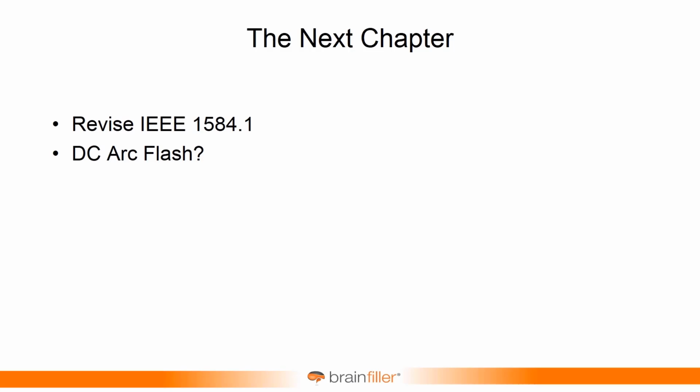The lower current cutoff, well, right now it's 2,000 amps. Are we going to be able to work with that anymore? I'm not sure. Because the problem with trying to come up with a low current cutoff, as I said, it's not a hard, fast number. There's the possibility under certain enclosure sizes, certain configurations, and smaller gap distances, you could sustain to some really low values. So that one's kind of up in the air at this point.